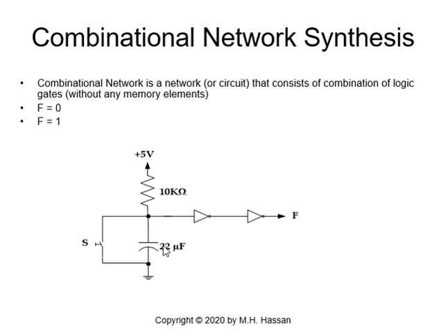At steady state, the capacitor will be fully charged and the voltage at this node will be equal to plus 5. When you take it to an inverter, you'll get 0 volt. When you take it to another inverter, you get plus 5 volt. Those are TTL inverters. The two TTL inverters are used to emphasize that the output is a pure one.